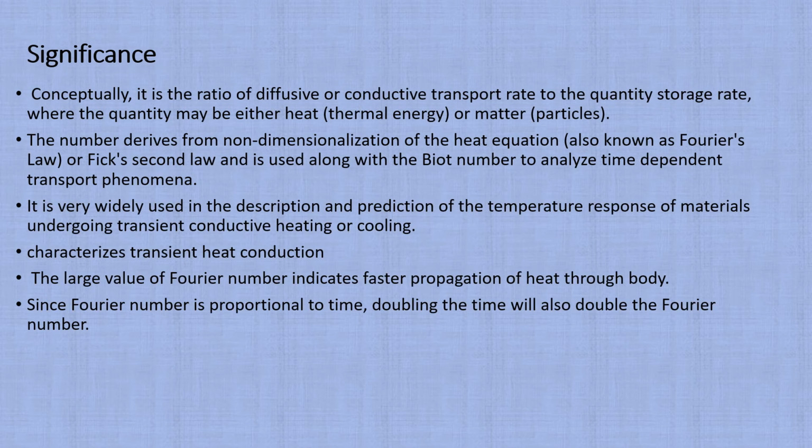Now the Fourier number is the ratio of diffusive or conductive transfer to the quantity storage rate. If we talk about heat transfer, then the quantity is thermal energy, and in mass transfer it is matter particles. The number is derived from the non-dimensionalization of Fourier's law or Fick's law, and it is used along with the Biot number to analyze time-dependent transport phenomena. Please keep this point in mind.